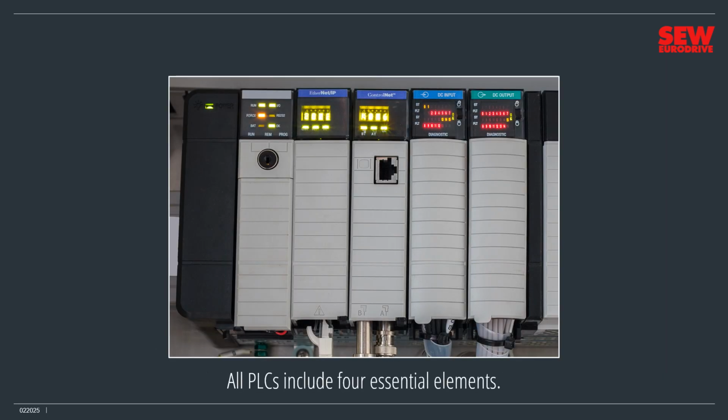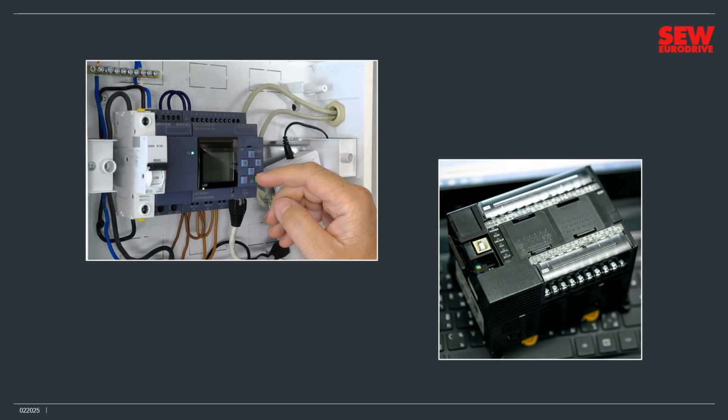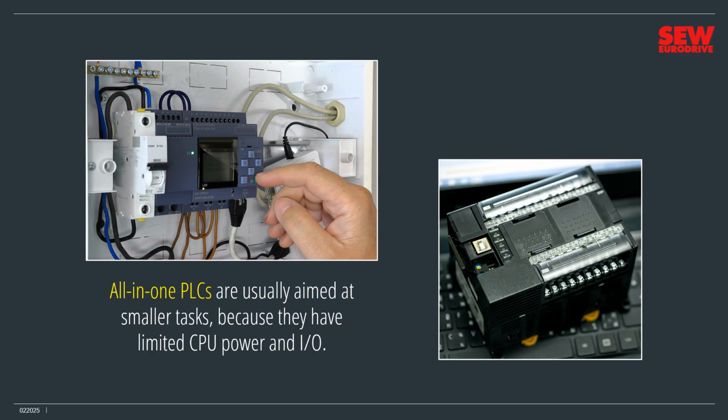All PLCs include four essential elements: a power supply, a central processing unit or CPU, a communications unit, and I/O. With an all in one PLC, these will be contained in a single enclosure. All in one PLCs are usually aimed at smaller tasks because they have limited CPU power and I/O. They're perfect, however, for many local control tasks.